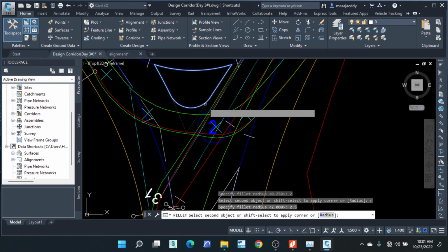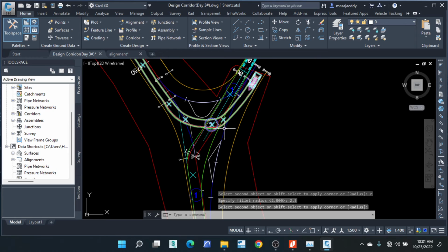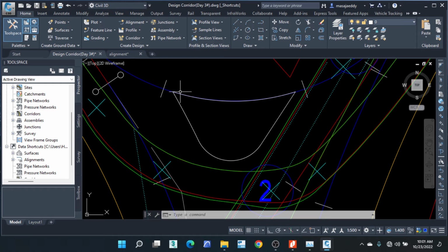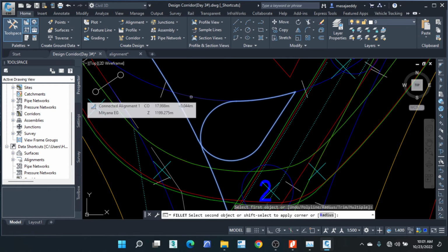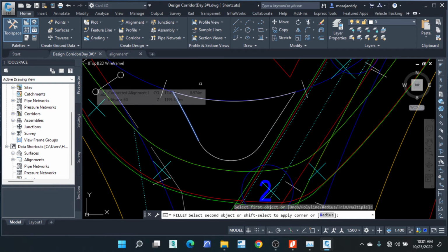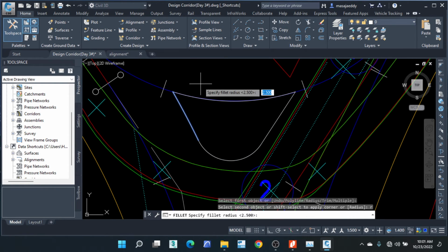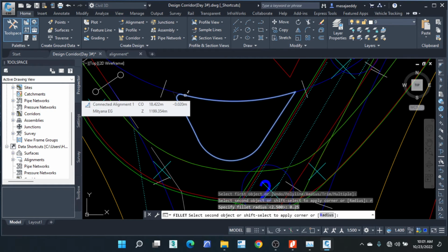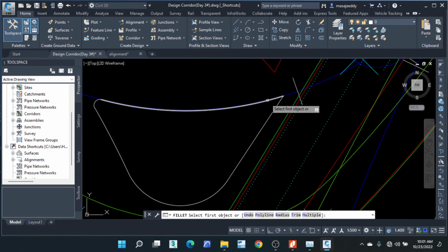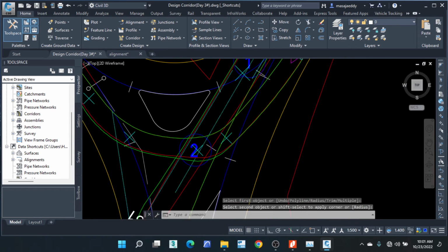Then come and look at this. This is better? Yes. Then the rest of them I'm going to chamfer, but I'm going to fillet, sorry, but without a very big radius. So I'm going to come here again. Come click on this one. If I'm to use the one that is default, which is 2, it will be a conflict. So I'm going to reduce the radius to 0.25 like I had said, 0.25, enter. As I click that, as you can see, I'm able to select. Then I'm going to do that again on this other side. Click on an area, come here, then you have that.